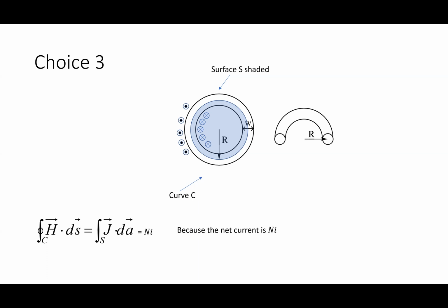Now, with the way that I've drawn this guy, how do I figure out the direction that that H field is going? Right-hand rule. So in this case, I got my current going in, right? So I guess I got to stand this way. So I got my current going in. My fingers are going to go this way, right? So it's going to go around the edge like this. All right, that's where my H field's going to be.